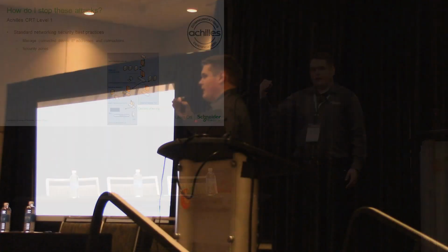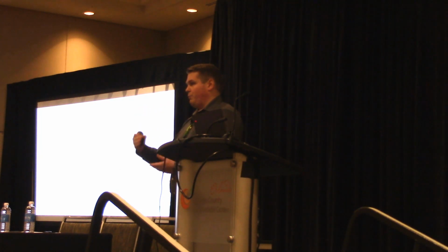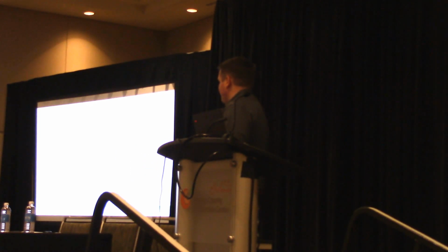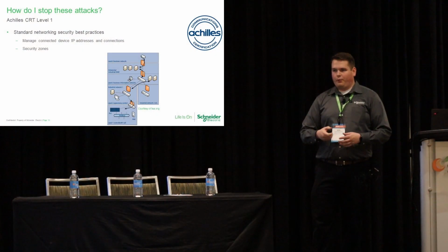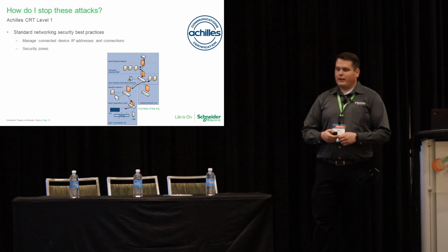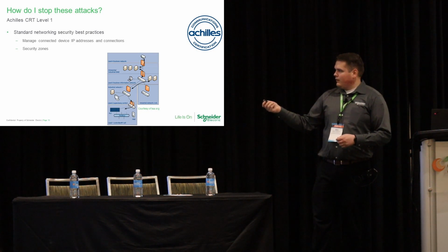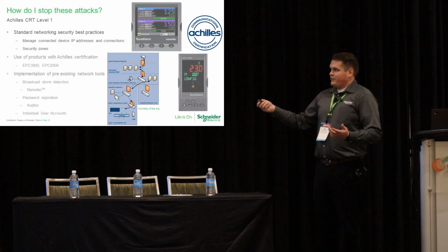Having firewalls as well as air breaks, where maybe your industrial side isn't connected to your front office side of things, is a really good way to go as well. But know the vulnerabilities, because with Stuxnet, they did not have that connected to anything. It was a localized system, but it was still attacked through just a worker plugging in a thumb drive or his phone to charge during the day.